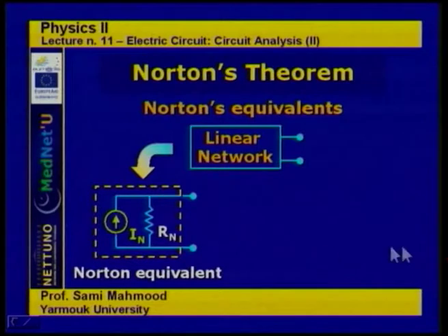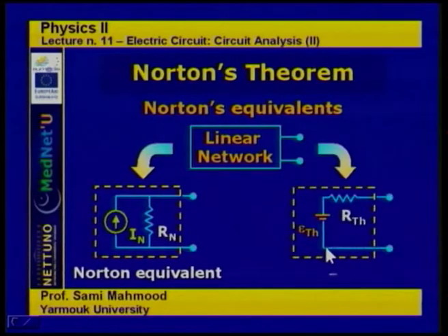This can be viewed, as we have mentioned before, the same network can also be constructed using Thevenin's theorem, and the Thevenin's equivalent, as we have discussed before, is simply a box that consists of R Thevenin and epsilon Thevenin in series.